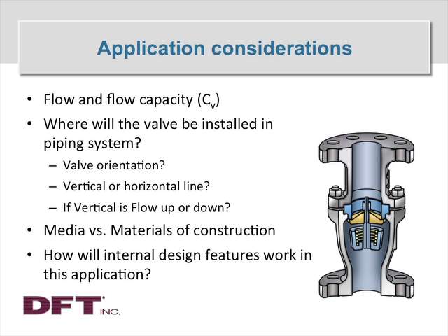Again, thinking back to the tilting disc and the swing check valves, will I be able to get that top access cover at the 12 o'clock or vertical up position? May not work. Those styles may not work well in a vertical line. They might work just fine in a horizontal line. If it is a vertical line, is the flow going up or is the flow going down? Those present two very different circumstances.